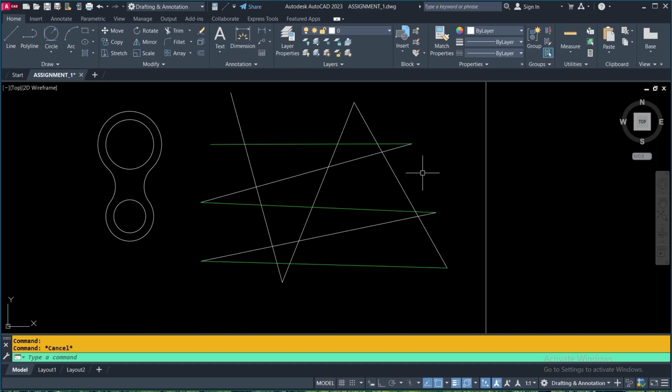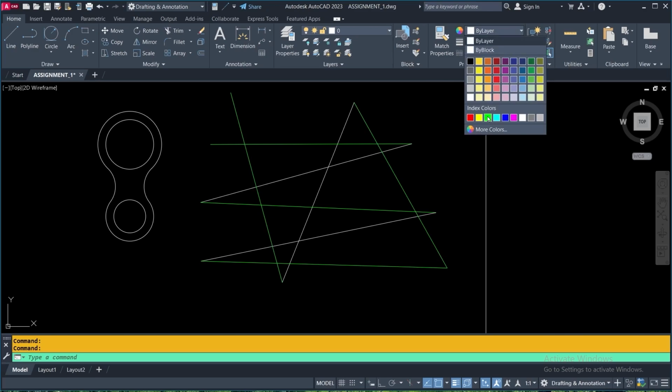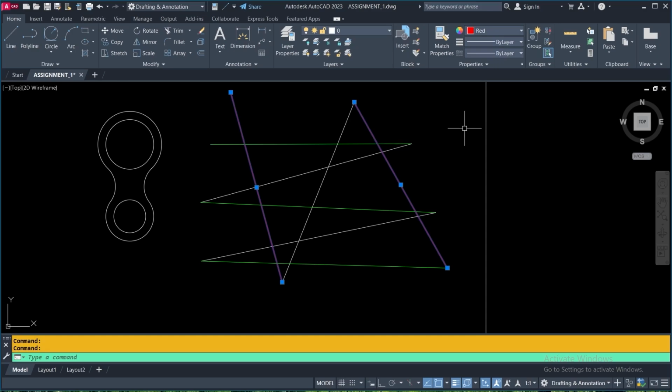In this way, if I want, I can select this one, and by clicking this one and going to apply color on them, that is going to apply properties, change properties on these 2 selected lines, and clicking here in the color portion, this is bilayer, click and selecting red color, click. Now they are selected, so I am pressing escape to cancel this selection.